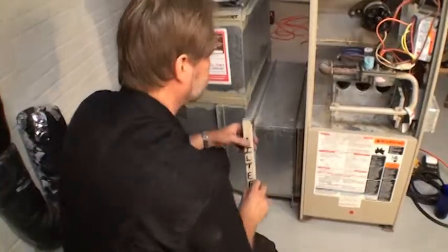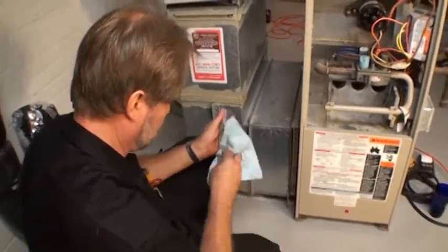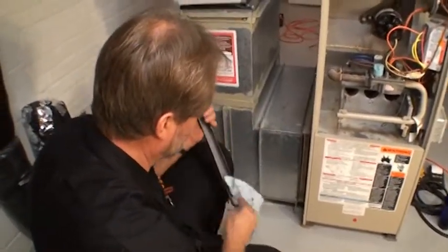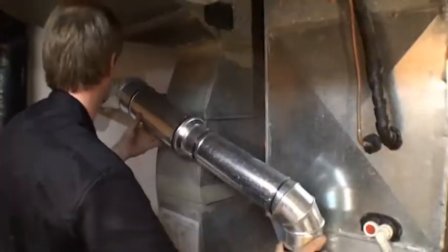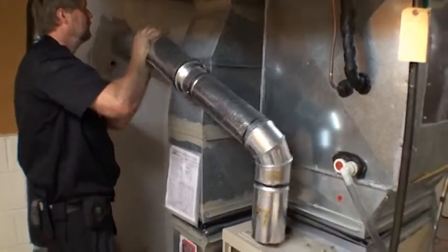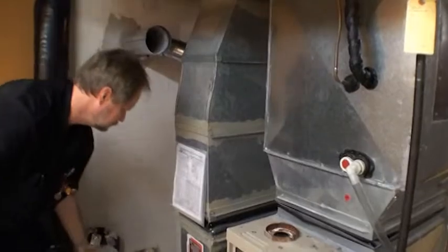Explain to the client the need to purchase a filter that allows for good airflow. If the furnace does not have a furnace filter cover, you will need to install one that seals tightly. Remove the furnace flue and inspect for rust, weak spots, and leaks. Clean and inspect the chimney's drip tee and ensure it is clear and drains properly.